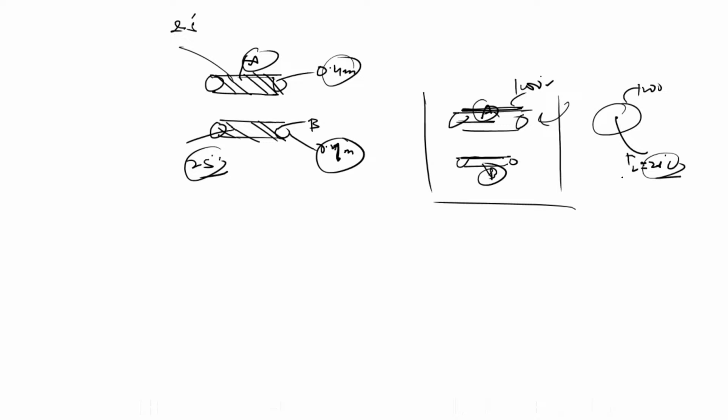Clear to you? As time t progresses, heat gets transferred by convection and then conduction into the solid, and the temperature increases with time. Yes or no? The temperature at any point within the rod will increase with time. And this is an unsteady state problem, because the temperature is not constant. It varies with time at any position.